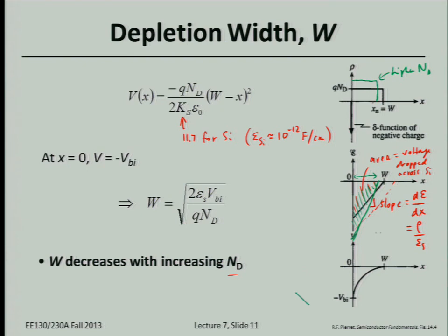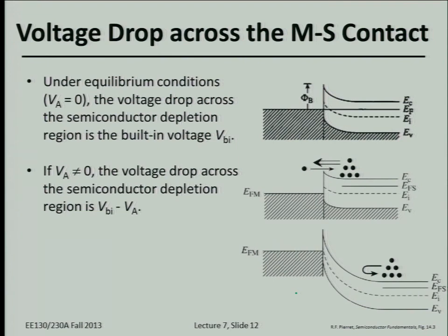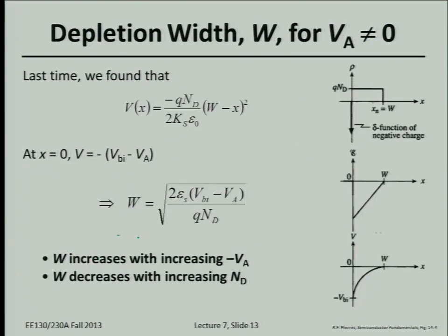So this form is important for you to remember, but this is not the actual equation you should memorize, and let me explain why. Because when we use a metal semiconductor contact, we always are curious how current flows as a function of applied bias. So let's see what happens when you apply a voltage across this device. Metal, silicon, let's say doped silicon, right? Typically, whenever we make a metal semiconductor contact, it's a moderately doped semiconductor. So let's say we apply a bias across this device, like this.